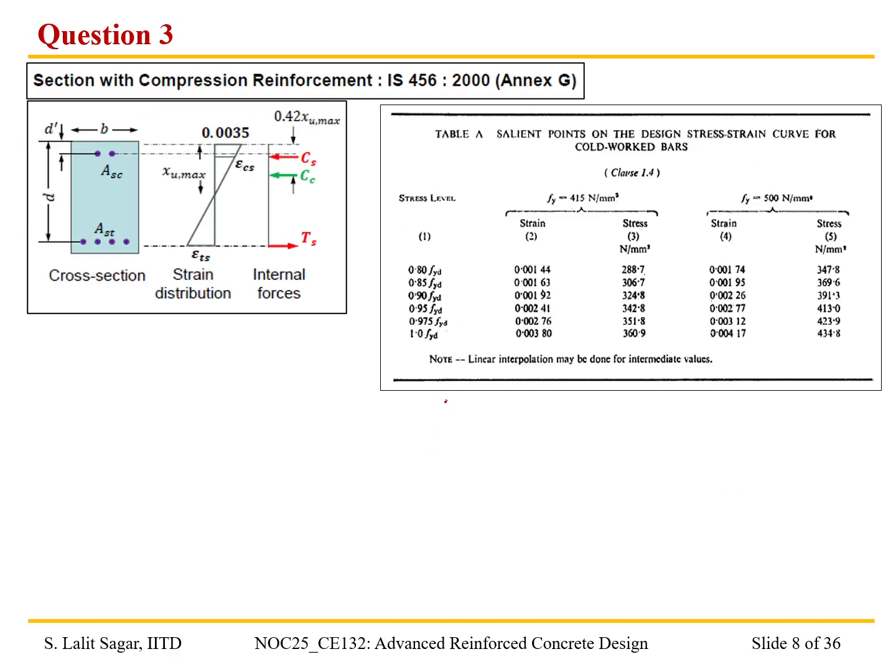Okay, so excellent. I think we are having the figures also here. So let me draw the cross section. Okay, then we can take the help of the Excel sheet in order to determine the moment capacity. Okay, so here is the cross section. So we have considered a square cross section of dimensions 450 by 450 millimeter. It is reinforced with 4 rebars of 25 mm diameter.